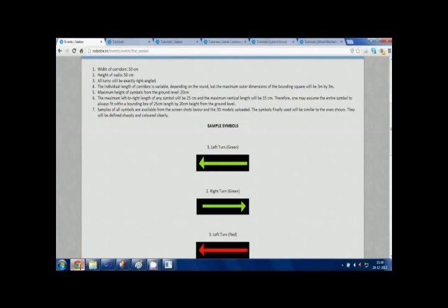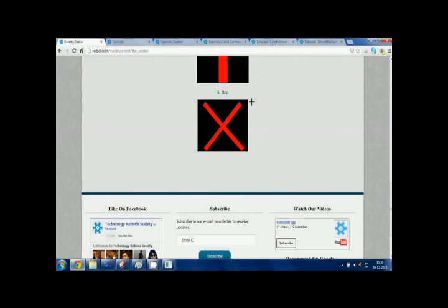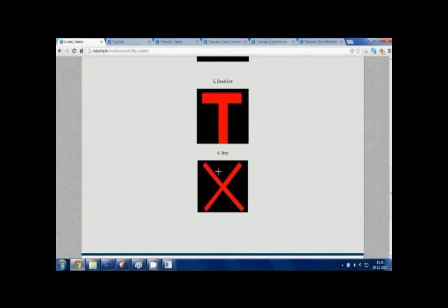Now at this point of time, there are multiple things you could do. We are not going to be giving you exact instructions. This is for you to test and find out, but suggestions could be, you could find the nature of these slopes, knowing that a particular set of slopes means that it's pointing to the right. This rectangle will be common for both a left and a right arrow, but these slopes may not be. If you have the stop sign, you can apply some other kind of Canny edge detection and apply some other combination of slopes. The same goes for a dead end.